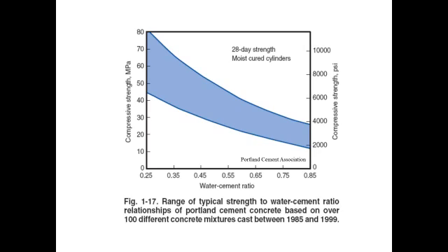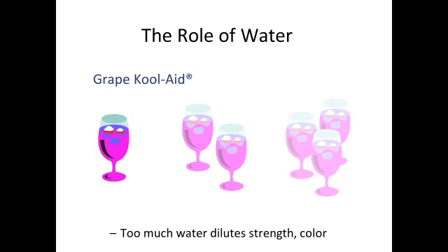I mean, everybody wants to use, or a lot of people want to use, a very low water cement ratio, but sometimes you just have to bump it up a little bit, maybe go from a 0.31 to a 0.32 or a 0.33, just so that your mix has enough fluidity so that superplasticizer, which I'm going to talk about in a little while, is effective. You have to let off the brakes to go forward in your car. So finally, if you add more water, you're diluting everything, and color is one of the admixtures that gets diluted. So your rich purple color becomes a pale lavender instead.